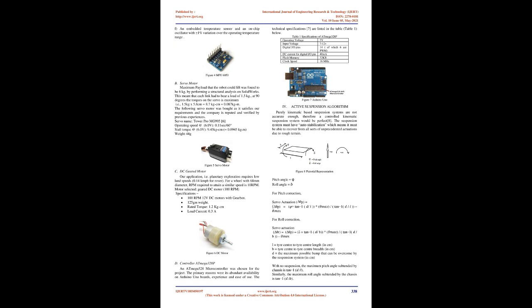This data would be fed to the microcontroller which will take action in case there is a disturbance in the orientation. We chose the IMU MPU 6050 for our purpose as it was accurate to about 0.01 degree and was cheap. B. Servo motor. Maximum payload that the robot could lift was found to be 6 kilograms, by performing a